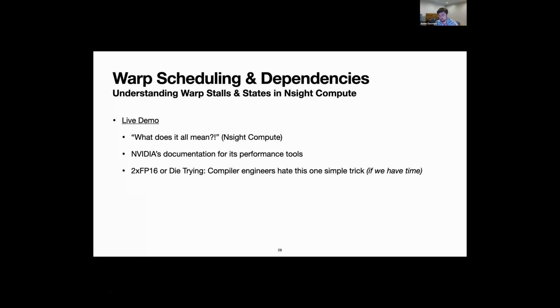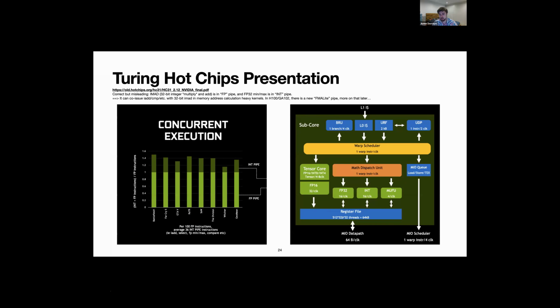The FP16 thing was just an interesting side note. Like Eric mentioned, HFMA instructions being in weird places. I could try to quickly find it in the live demo, but it's not that interesting. Sometimes NVIDIA is using some of those other pipelines to do something like a move that just copies a register, because that's the pipeline that's free on that cycle, or for some reason it's actually the more efficient pipeline to do it on power-wise or whatever.